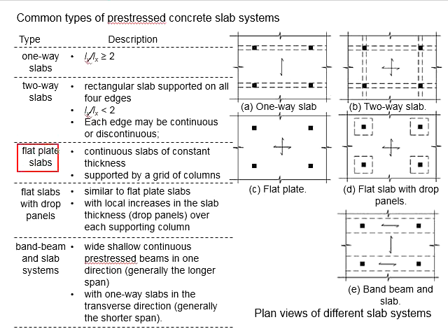Next is the flat plate slab. It is basically a slab with a constant thickness being supported by a series of the columns. There are no beams between the columns and the slab. Therefore, whichever load is being distributed, it will go directly to the column.